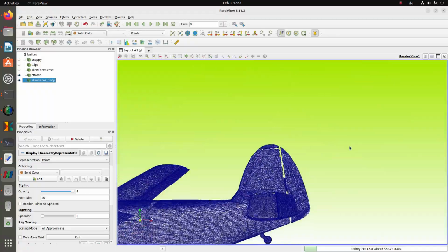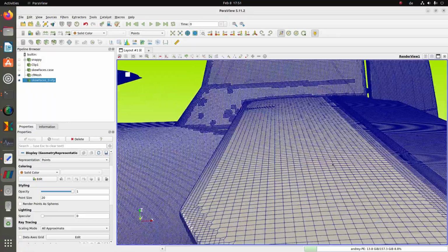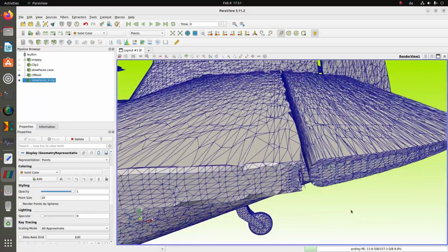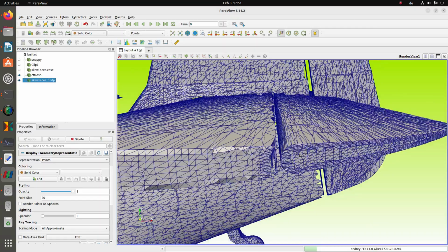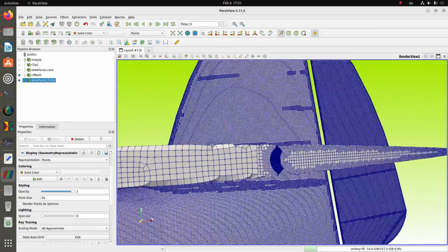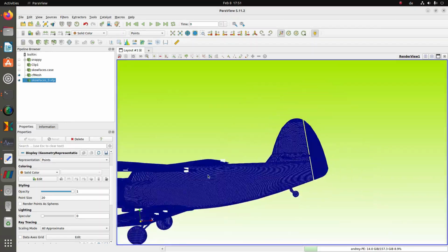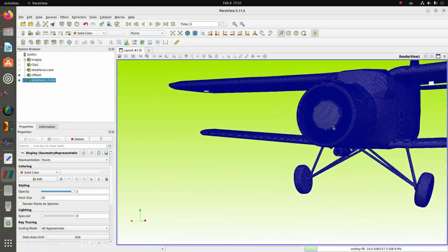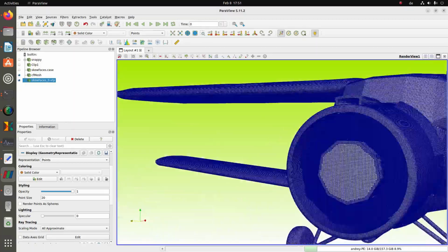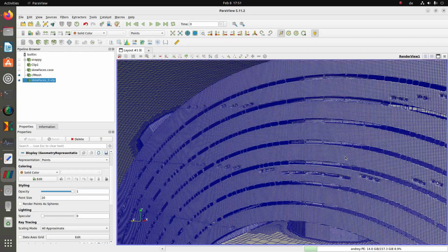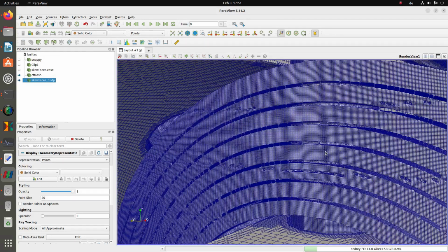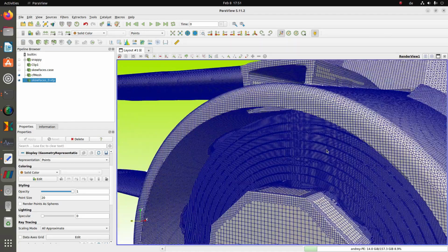Now I go to horizontal stabilizer and look on elevator. Walls elevator looks also good. So the one problem is the missing of cooling ribs. The cells here are destroyed.